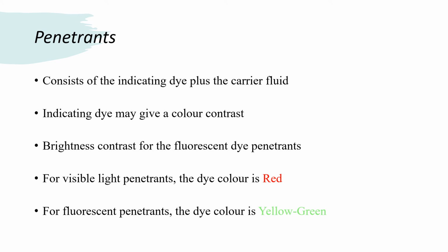For the visible light penetrant, the dye color is red, and for the fluorescent penetrant, the dye color is yellow green under the ultraviolet light.